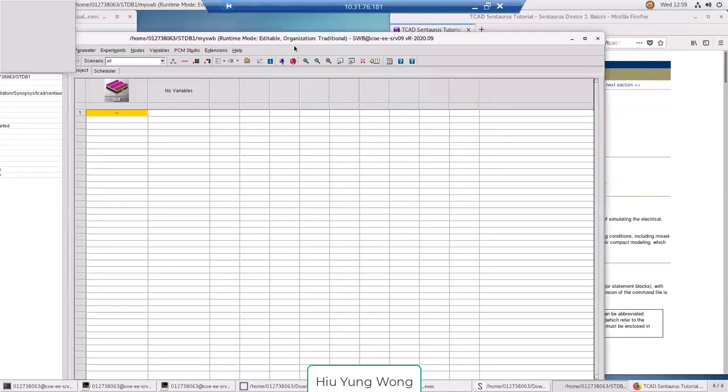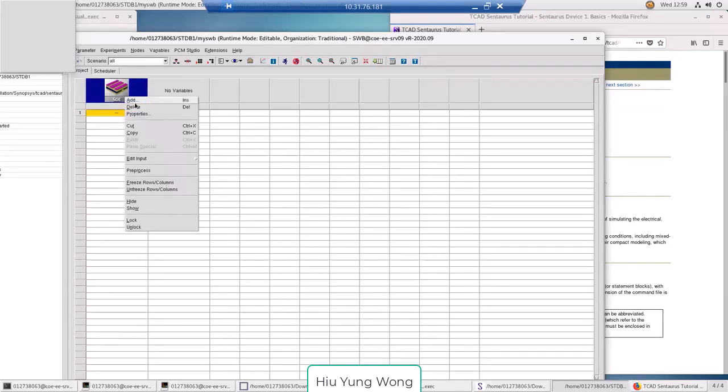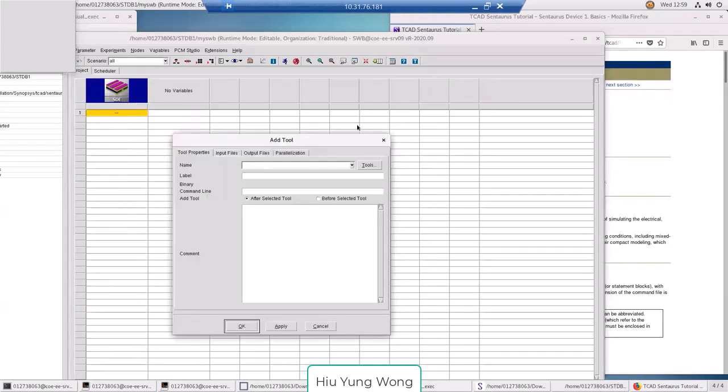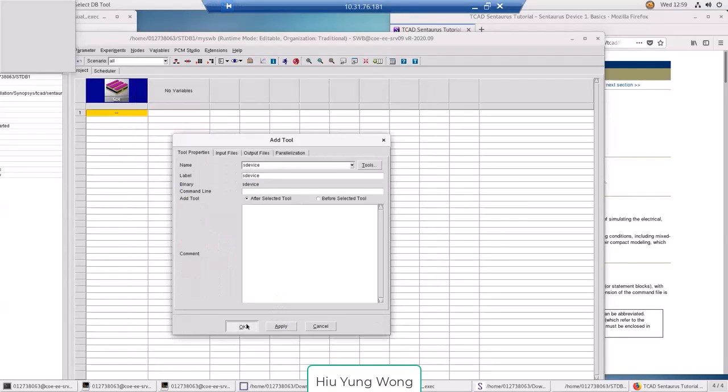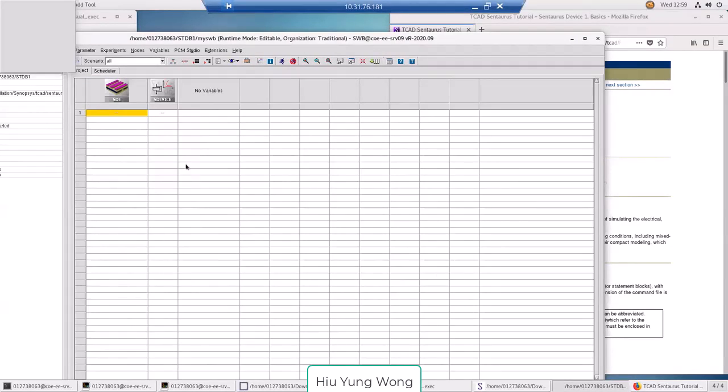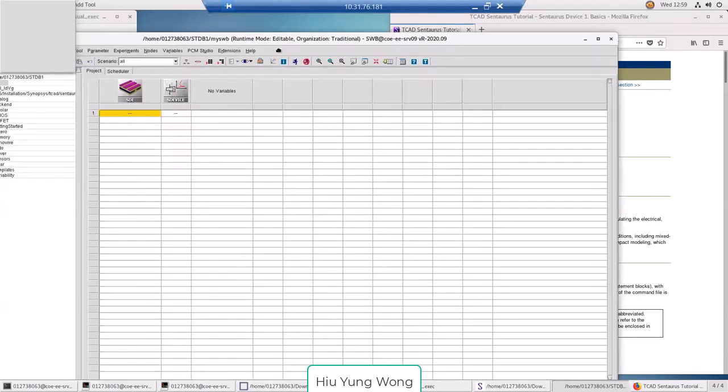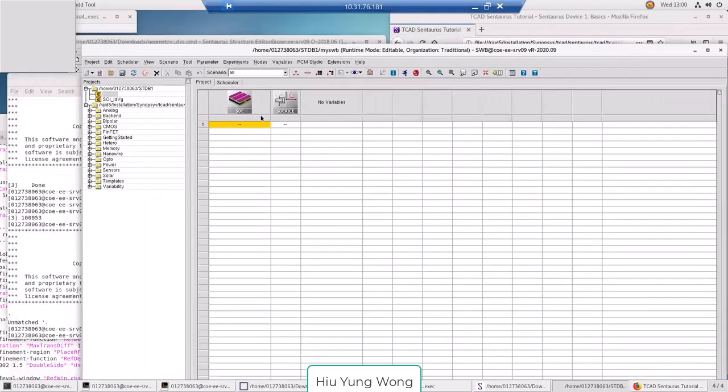Okay, so now imagine you are in the lab and you want to do measurement, right? Someone created a device for you. You want to do measurement, but you are doing simulation, right? To do measurement, the first thing, right click, add a tool called S device, right? Can you do that? I will go fast. If you cannot follow, let me know, and then I show you again. Use the project you did yesterday, in which you already incorporated your device.